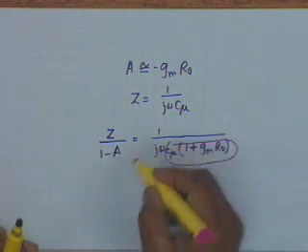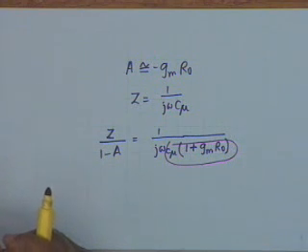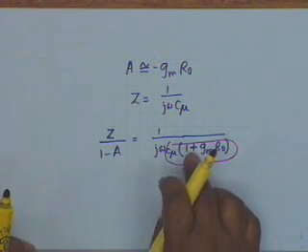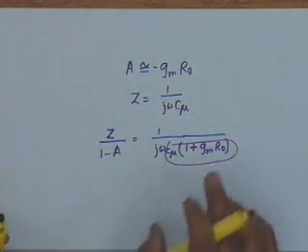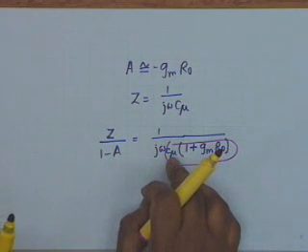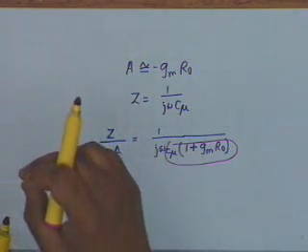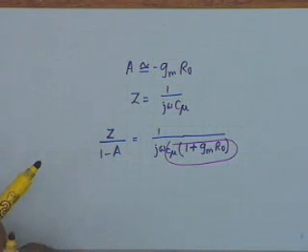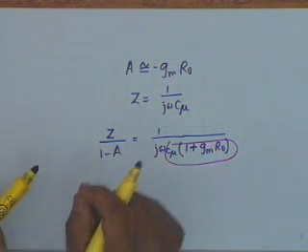C mu is a small capacitor of the order of 3 pF, and C mu is now multiplied by 1 plus the gain of the circuit. If the gain is 99 and C mu is 3 pF, equivalently it is reflected at the input across C pi as 300 pF. Is the point clear? Even a small capacitor can cause devastation in the input circuit, because it can swamp C pi. C pi is only of the order of 100 pF. And if the gain is 1000, well, 3000 pF. C pi can be safely ignored. This is what the effect of C mu is. Even though it's a very small capacitor, it can reflect at the input as a large capacitor.